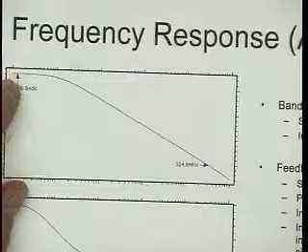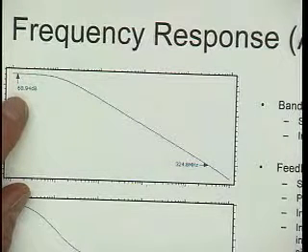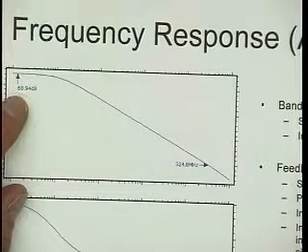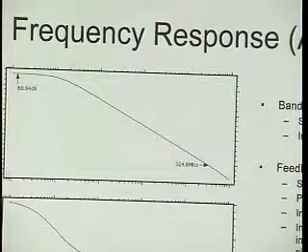So here I get the gain, and the gain is here 70 dB, so that would be almost 4,000 or so. Well, about 3,000, right? Which is what we said that we get when the amplifier input and consequently output are just at 0 volts. VOD equals VID equals 0 volts.